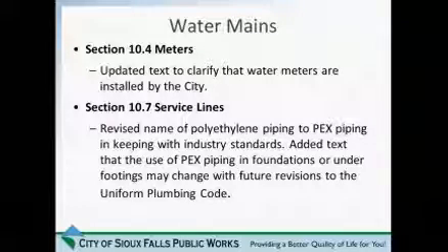In addition, under that service line, I wanted to have some language in there that kind of trumped our design standards when it comes to the Uniform Plumbing Code. Sometimes they have different types of requirements for water services as they run from 5 foot outside of the building up underneath the foundation into the meter. And if they no longer allowed plastic pressure service tubing or PEX service piping, I didn't want that in the engineering design standards. So that's about all I have on Chapter 10.